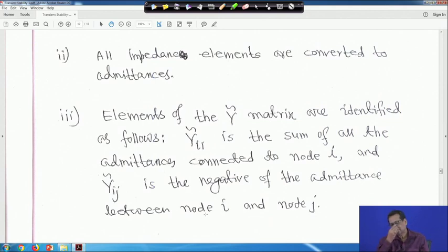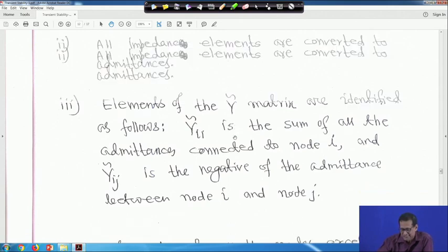That is why in the load flow studies, in that Y matrix, we use capital Y11, Y12 like this. But when we find the admittances, the diagonal admittances, all small y are added, and all your off-diagonal elements, capital Yij, are equal to minus of small yij. It is the negative of that, right. So, that you have studied from the load flow studies.